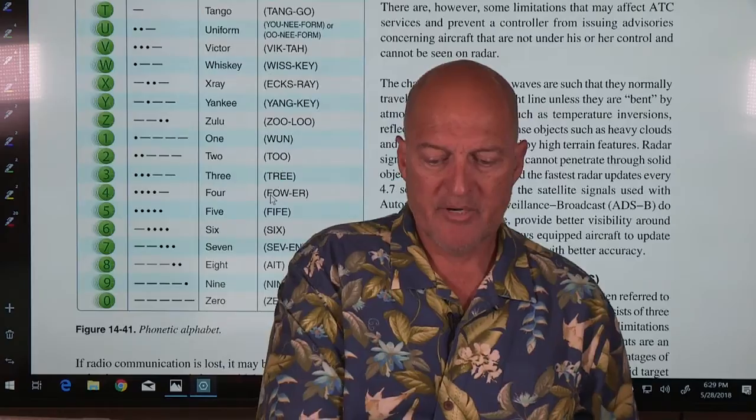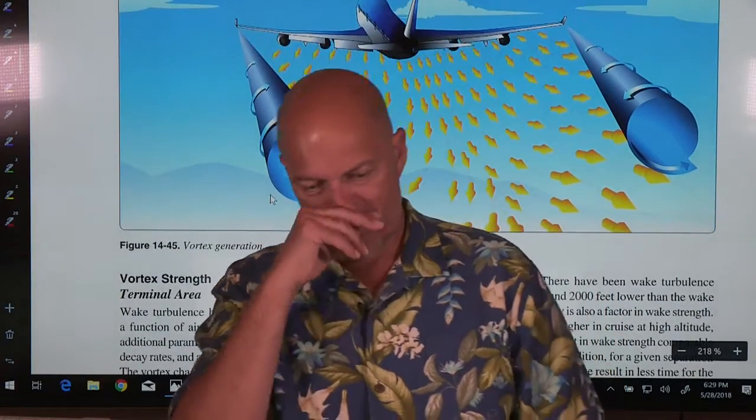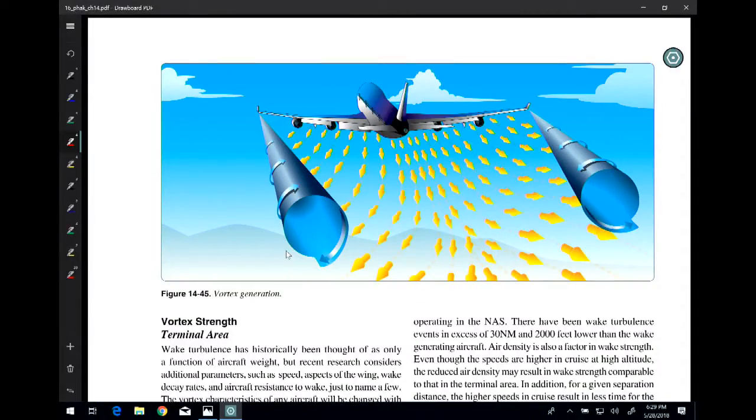What is wake turbulence? Well, let's take a look over here and find out what wake turbulence is all about. First of all, when is wake turbulence generated? When do these vortices begin? Those of you that said when the wing is creating lift, give yourselves a pat on the back. Wingtip vortices exist anytime that aircraft airfoil is producing lift. They produce vortices.